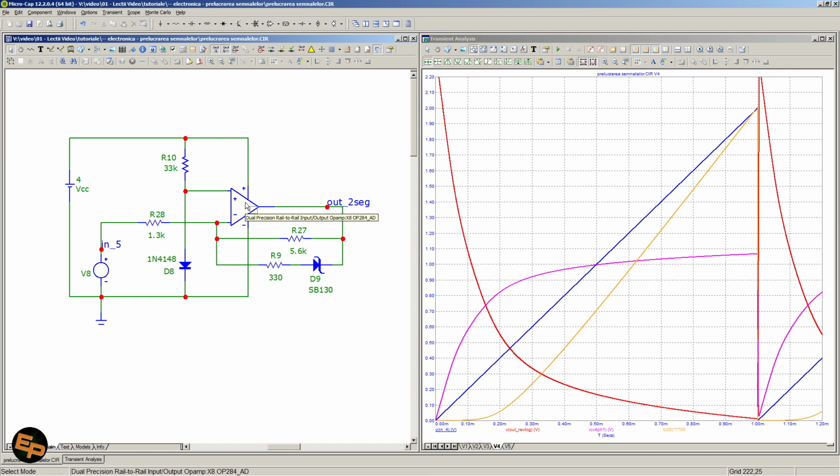It has only 1 op-amp, fewer components around, just 2 diodes, and also this fifth circuit is different from all the other 4 in the sense that I've simulated it with a single power supply of 4 volts and a rail-to-rail op-amp, because in my case this is what I needed to have in the end.